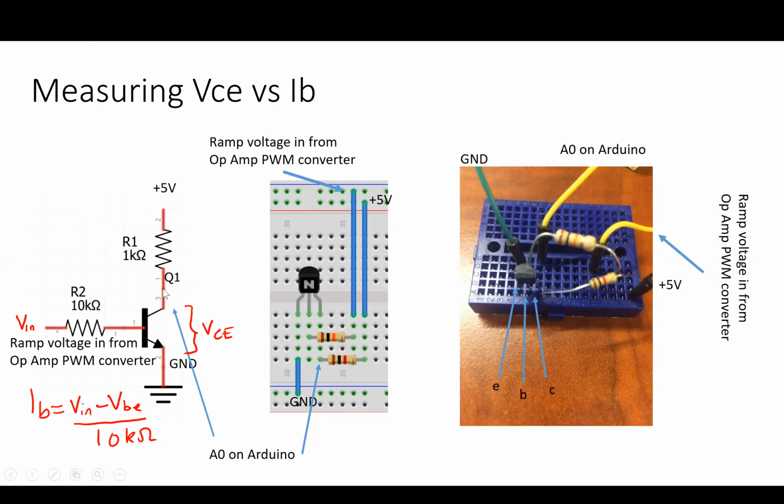The voltage at this point is not driven by the ramp anymore. It's held constant at whatever the Arduino maximum voltage is. So now the current through this resistor will be given by this voltage, which in my case is actually 4.91, minus the red voltage. And so the voltage across this resistor divided by 1K will give me the current through it.